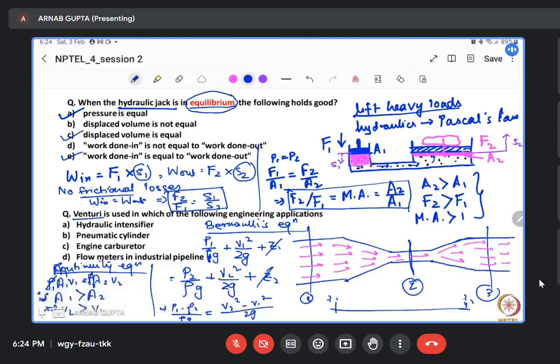That is basic intuition, because the fluid is trying to flow through a smaller cross section, so it needs to increase its velocity to maintain its discharge, right? So that's why the velocity of the fluid will increase. Now you see, since V2 is greater than V1, essentially that increase in velocity head needs to be compensated in the pressure component of the energy.